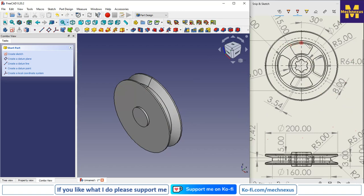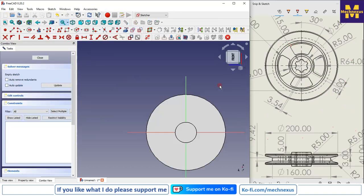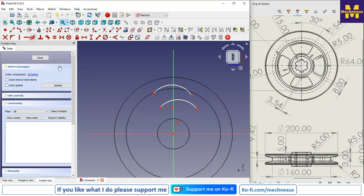we will make this slotted cut. So I will select the face and create a sketch, and I will select the 3-point arc, one this and the other one is this, and I will switch to the wireframe, and I will make it vertical.